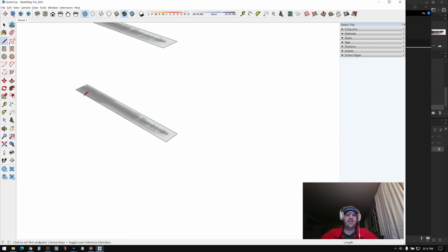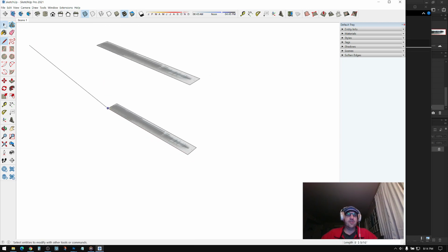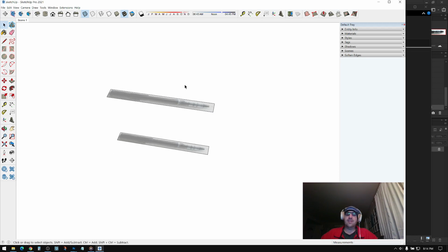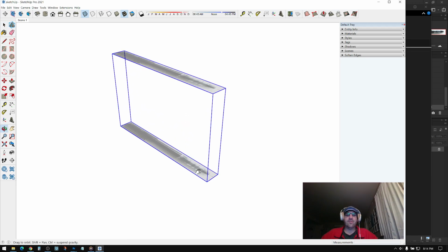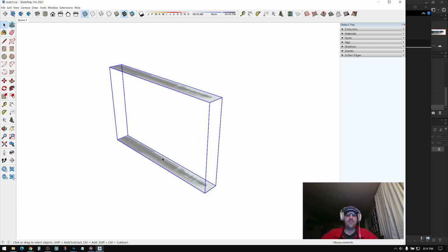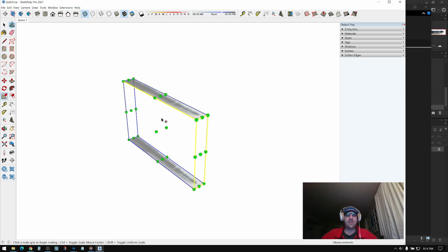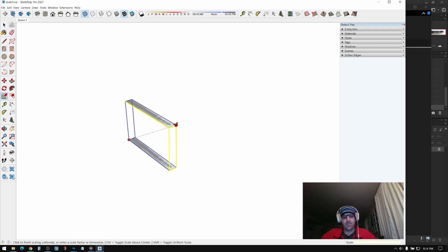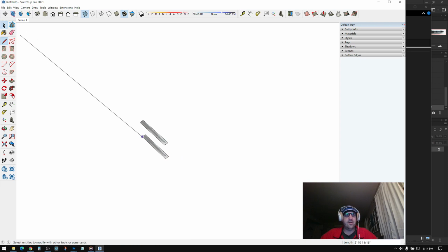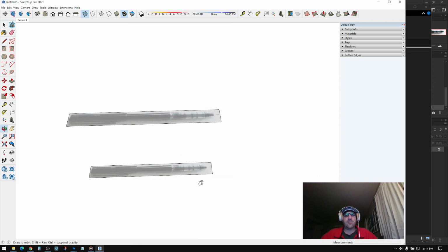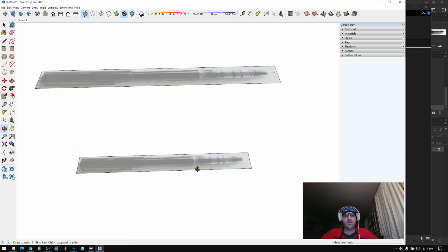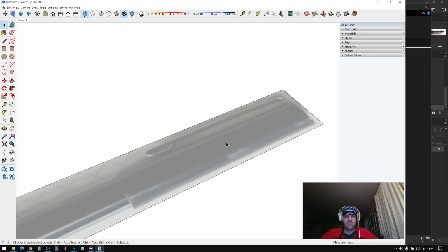So instead of 5 inches, it should be 50 inches. It's 4'2". It will just make it easier to model, and it's something I've learned over the years that the units are easier to model at a bigger size. When I'm done modeling it, I'll scale it back down by typing in 0.1, enter, and it will go back to 5 inches, the proper scale. Right now I'm going to model it at 50 inches. I'm going to explode my group again and start modeling.